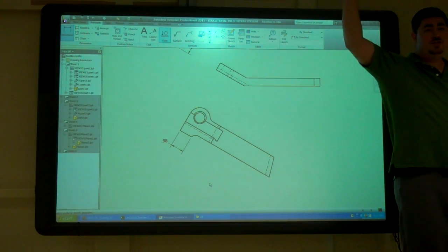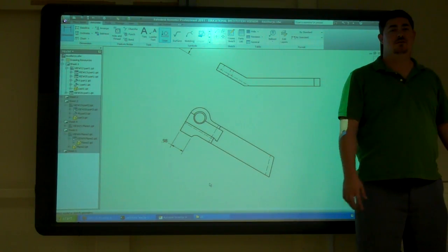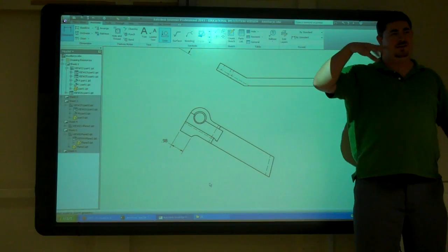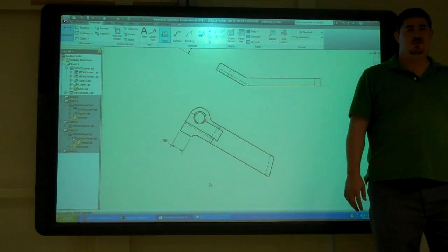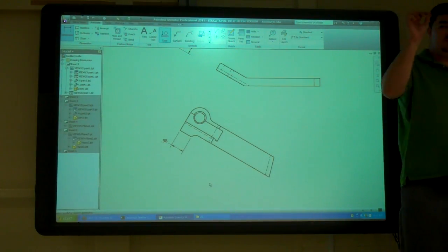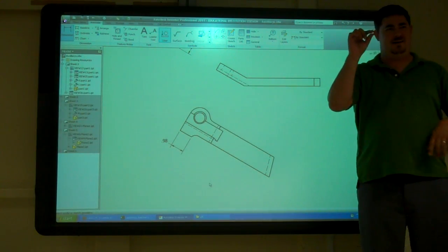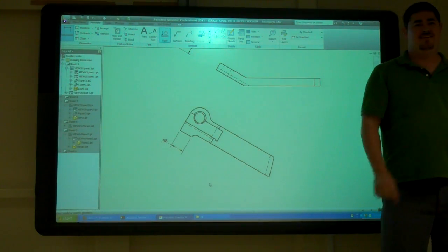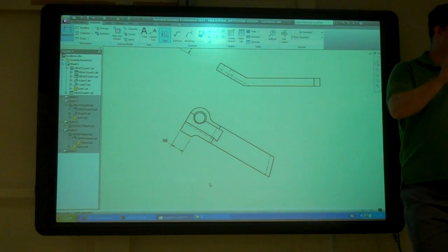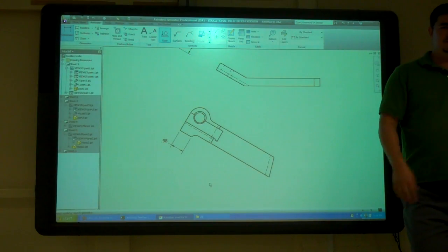Okay? So find the true shape view and dimension it, or at least 2 or 3 sides, or on the planes, yeah, dimension all 3 sides, so we can see what the lengths are. Okay. Questions? And if you zoom in on those planes, you'll see a little bit of an edge when you're on it. You'll see 2 lines when you're on an edge view, because in order to make it solid, it has to be thick, and so I made it like 1/10,000th of an inch thick. So you might see that there's 2 things, but don't worry about it. Pretend like it's flat.